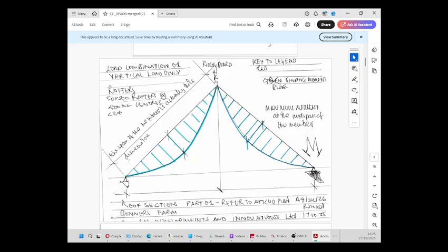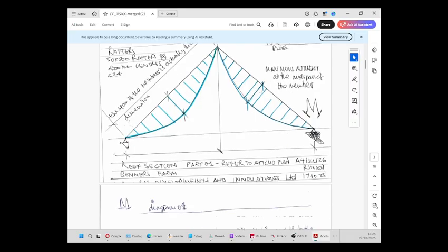The span of the member is actually this dimension, which is cos of half of the width of the roof. So cos 35 equals half of the width over the length of the diagonal span of the rafters. So the diagonal span of the rafters is equal to half the width over cos 35, and the ridge board is just holding them up. That's not doing anything structurally. The maximum moment is at the midspan of the members.